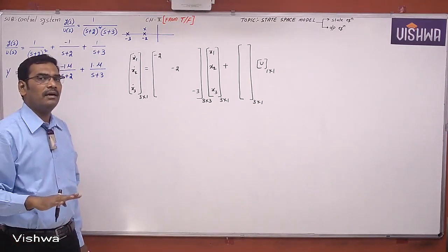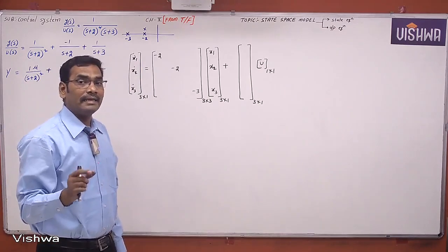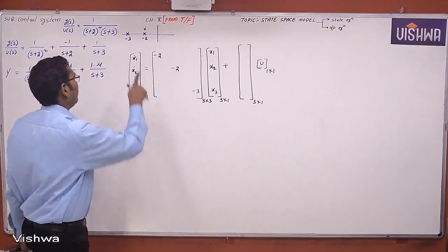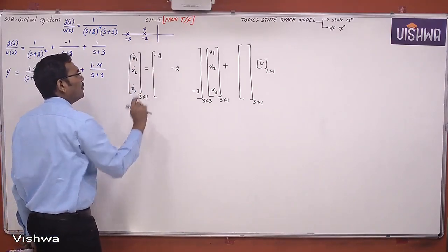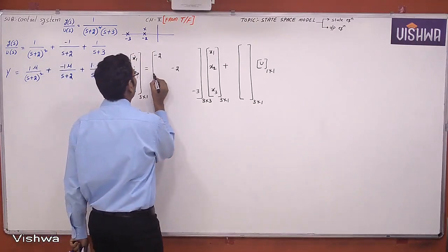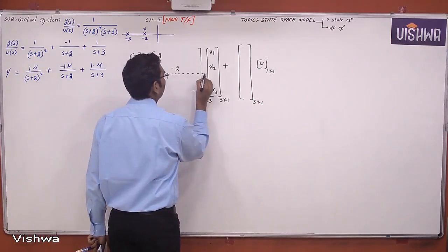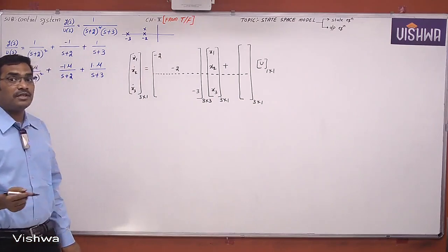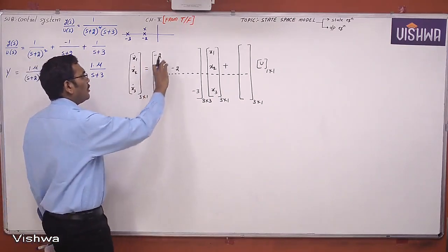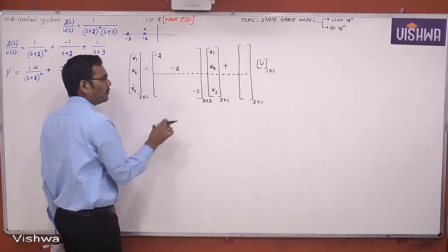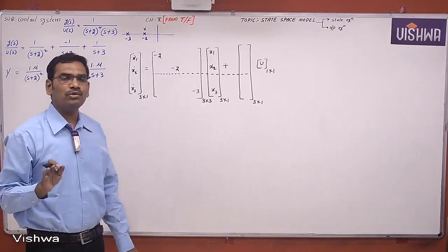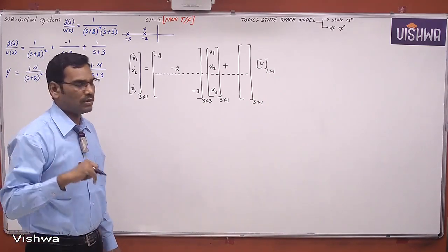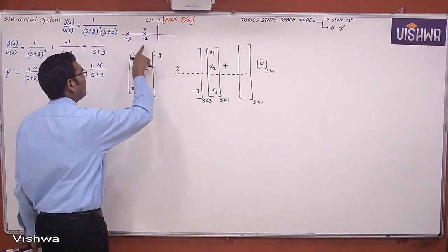After writing the closed loop poles in diagonal form, then you take a separate block, which will be the number of repeated poles. The number of repeated poles is 2, so you take a 2 by 2 block separately, 2 rows and 2 columns. Some students ask, sir, why are you taking this 2 by 2? You may take the bottom 2 by 2 also. Yes, that is also correct. You should take a 2 by 2 matrix where the quantities must be the repeated poles. That block will be the repeated closed loop poles block.